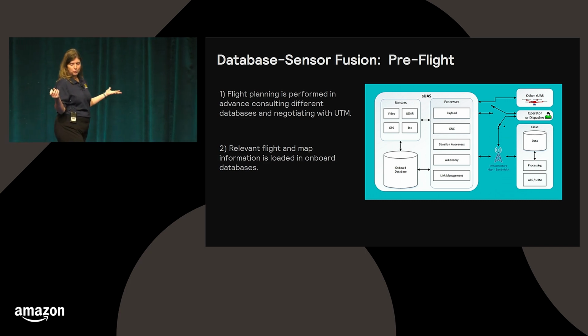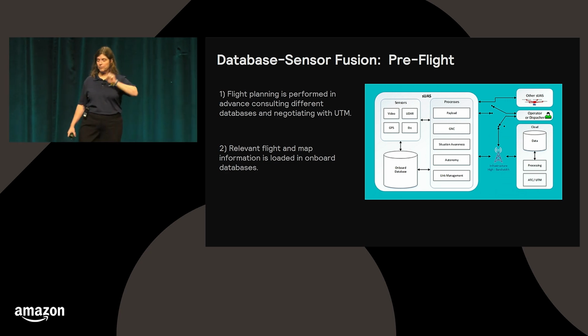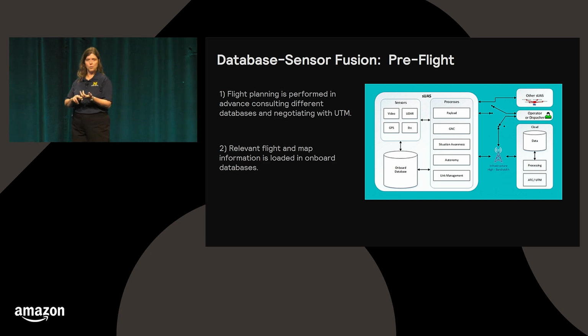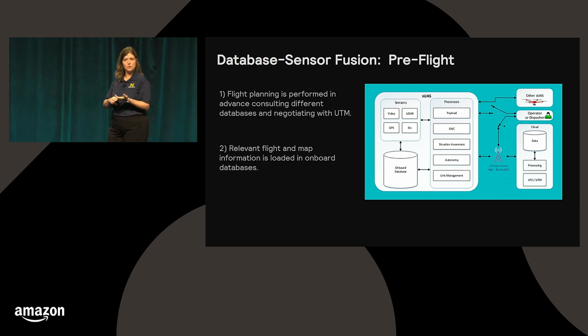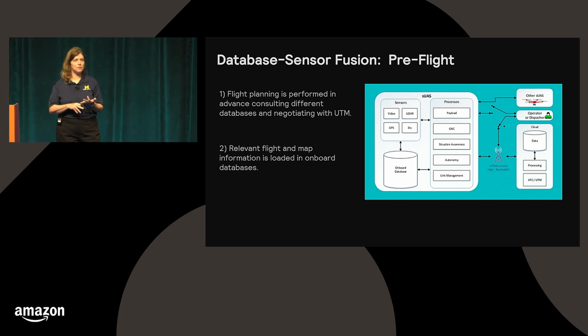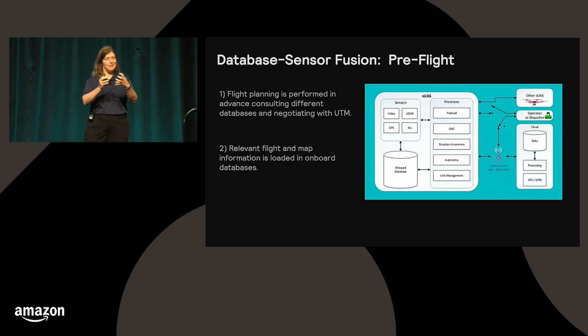So then what you want to do is to have the small UAS in this picture use all of the sensors on board. And you heard Amazon yesterday say, I think they were using video, thermal, and ultrasonic sensors to sense their environment, and then you would supplement that with inertial navigation systems, which would give you GPS and attitude information on board. That gives the vehicle the ability to sense its own state and the state of its environment.